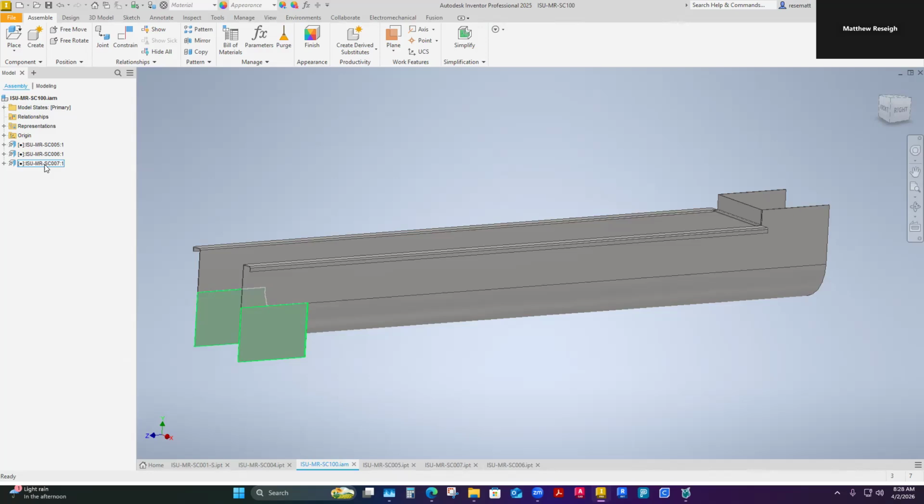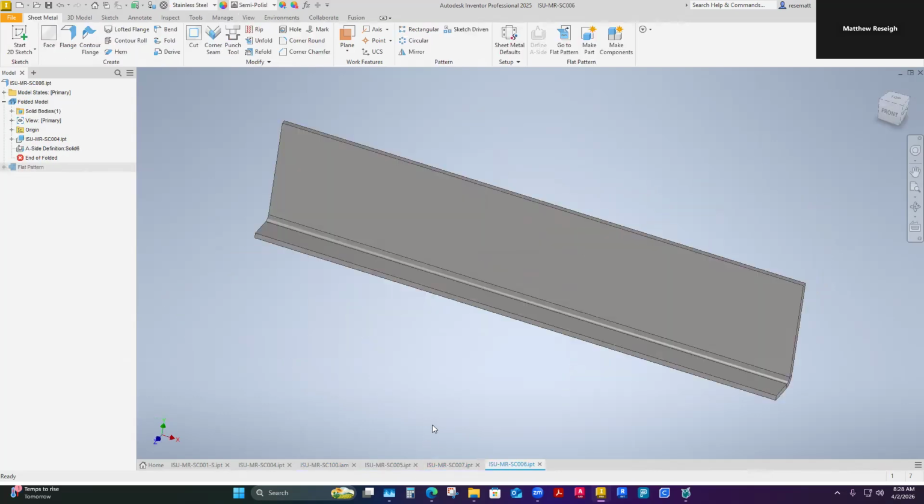It can be a problem if you want to get to an assembly and have some animation done on the assembly. Then we've got to maybe bring it in differently because of the constraint issue. Sometimes you need to relieve constraints in order to make some animations. So it doesn't work for everything. These parts are not going to move in an animation necessarily. So this would be a great reason to just make components, have them pretty much ground and root themselves in the assembly. And then all three of these parts are now individualized with their unique names that live in my part folder, and there they are.